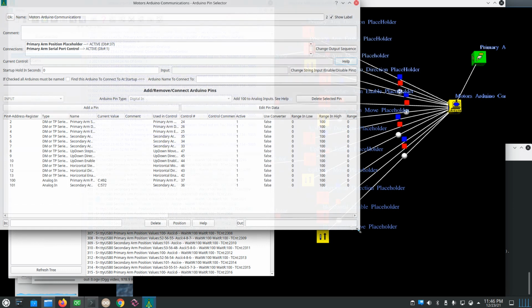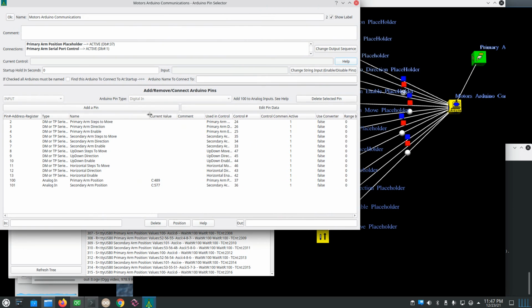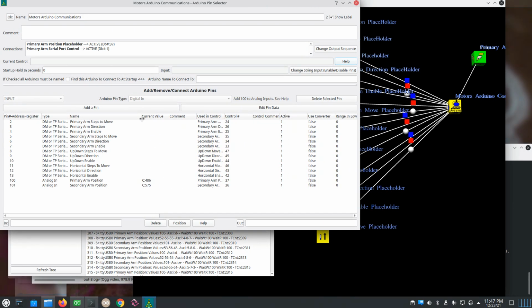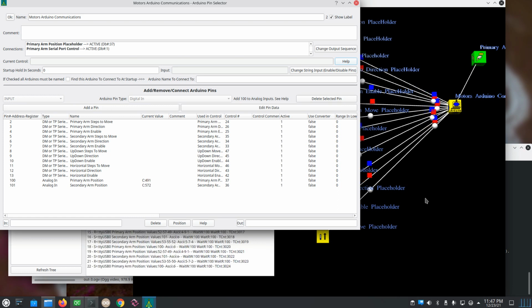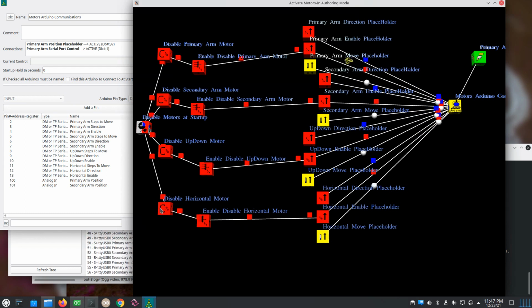because stepper motors take power when they're running. Even when they're not running, they take power, and it takes about an amp at 24 volts to keep it fired up all the time. So if you have 4 stepper motors, there's 4 amps being used when they're doing absolutely nothing. So I disabled them right at the start. Plus they run a little hot, and I don't need any extra heat. So that's the purpose of these constants here.